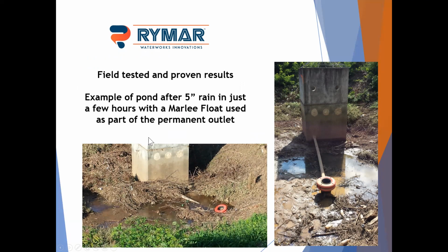And that afternoon we got a huge rain, about 5 inches in just a couple of hours. All the trash and debris got washed down into the pond. You can see our skimmer here with all these sticks and leaves around it, but it did manage to drain. Had it been clogged, it would have been easy: just pull the rope, and the rope doesn't show up well here, but it does have a rope on it, pull it over to the side and get to it.